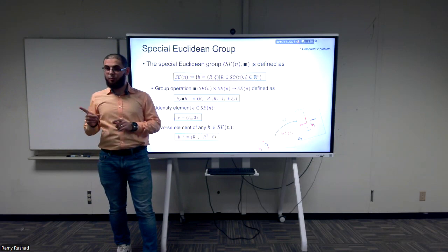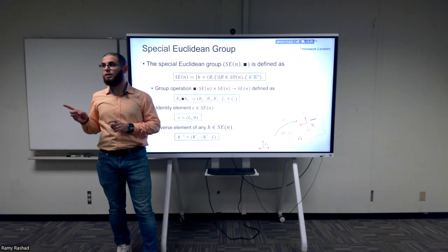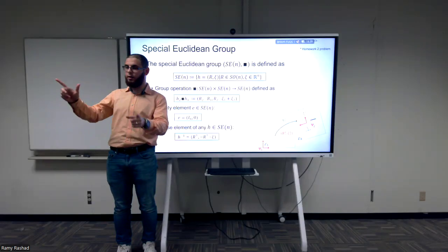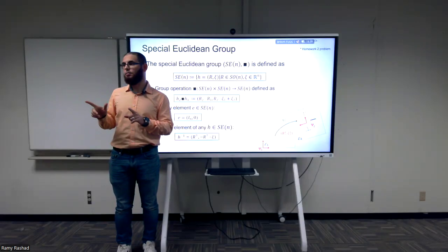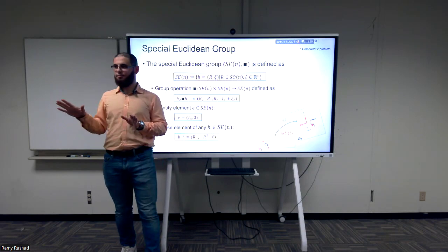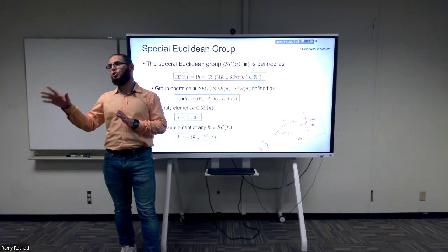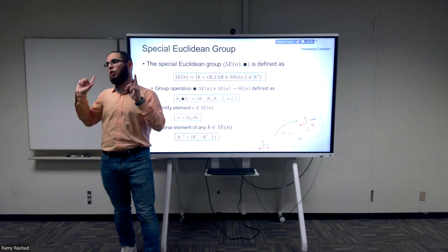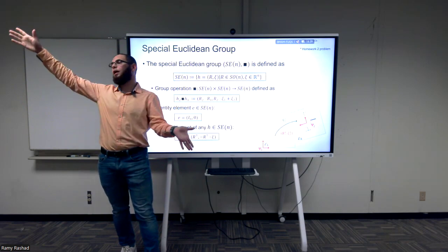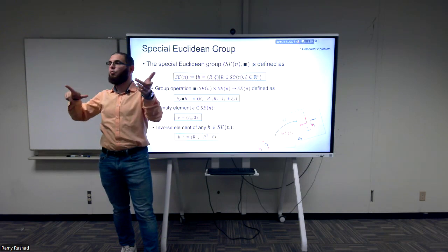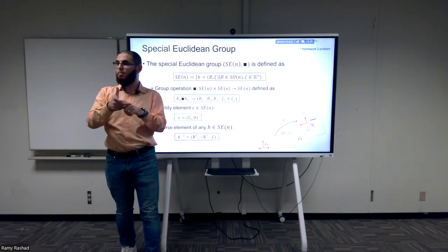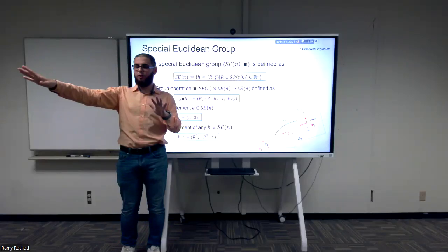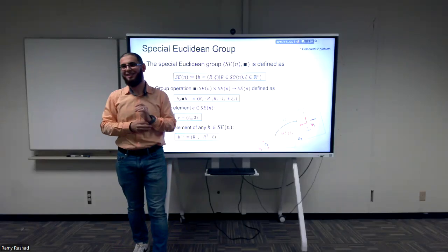For the same rotation, you can have multiple rotation matrices. No. For one rotation, you can have only one rotation matrix. It's always the case. That's the problem of the Euler angles. You see, representing the rotation matrix by 3 numbers or 3 angles, this is not unique. I can give you 12 possibilities of 3 numbers that will give you the same rotation matrix. But if you have a rotation matrix, then it's one-to-one to the abstract rotation, the abstract orientation. It has to be. And this actually gives me a nice idea for a homework problem. Okay, so it will be in the homework.